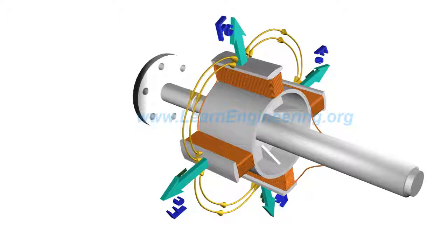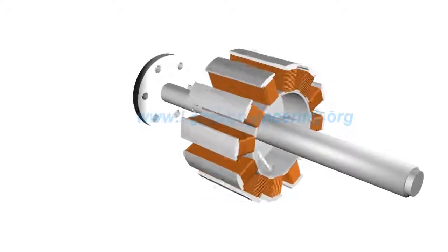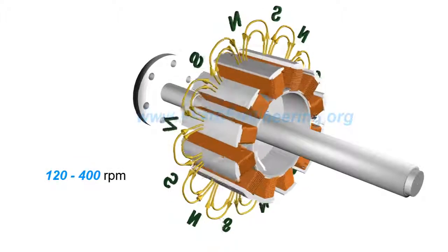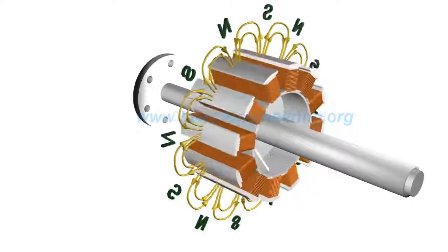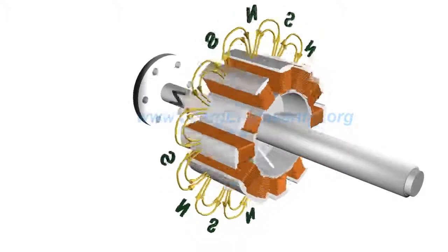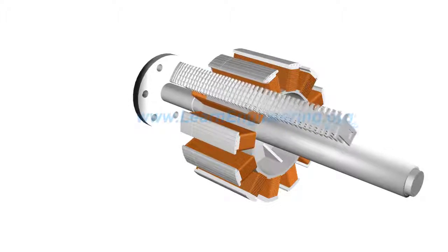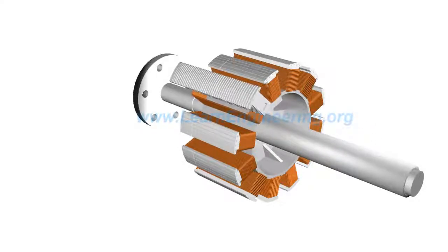So salient pole rotors generally have 10 to 20 poles, which demands lower RPM. Or, salient pole rotors are used when the prime mover rotates at relatively lower RPM. Pole core is used to effectively transfer magnetic flux, and they are made with fairly thick steel lamina. Such insulated lamina reduces energy loss due to eddy current formation.